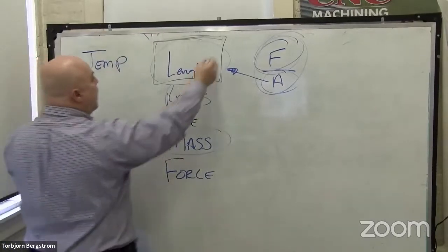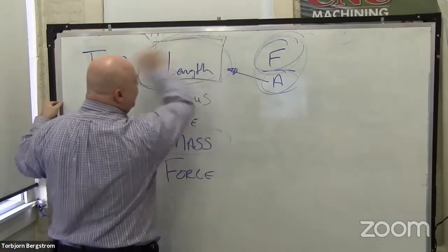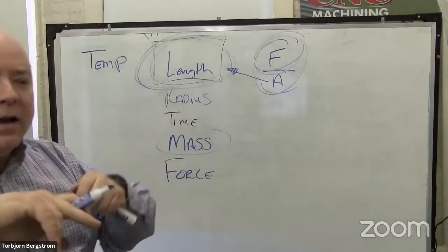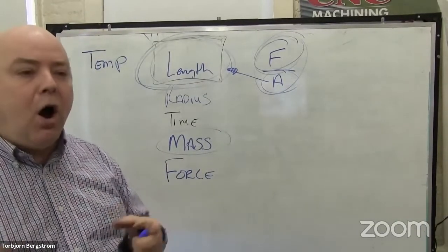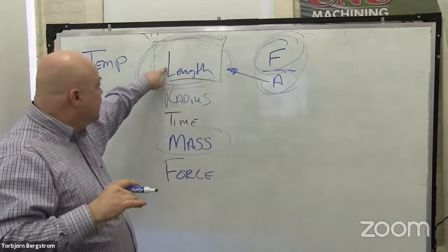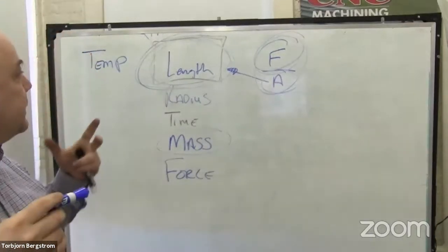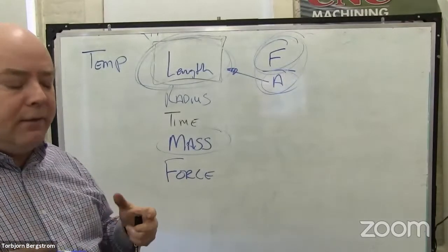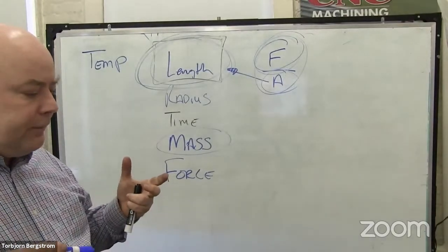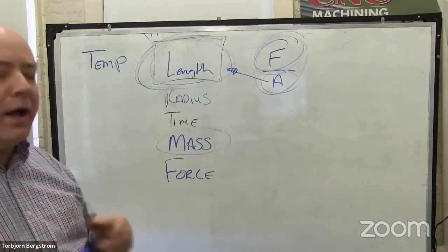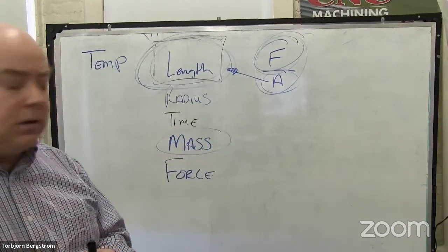In fact, if we want our length measurements to have any real value, one of the things that can cause that accuracy to be off is the temperature changing between length measurements. Because most materials that we use in engineering have fairly high thermal expansion coefficients, they move a lot with changes in temperature.